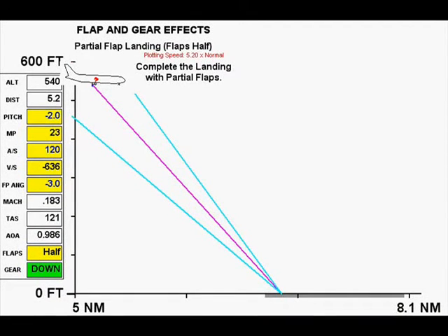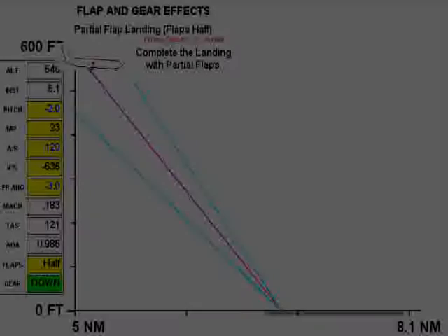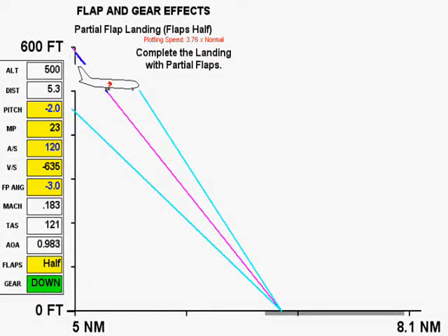This airplane's normal approach speed is 90 knots, but 120 knots is used to keep up with jet traffic. This means that most light airplanes will be flying ILS approaches with partial or no flaps. The landing can be made from this condition as shown here, with a resulting long landing distance. This is not a problem since most ILS runways are long enough to accommodate jets.